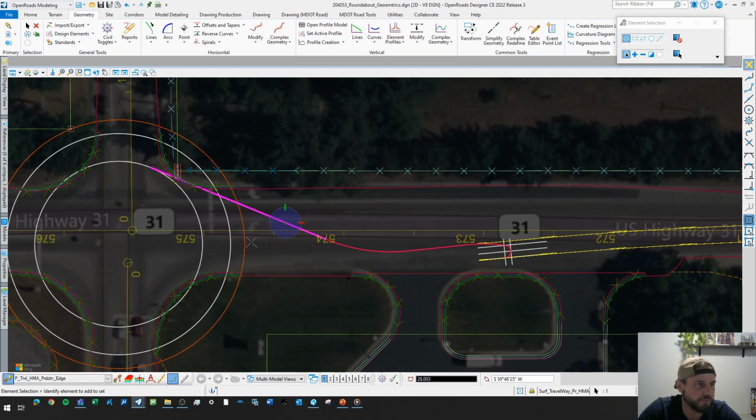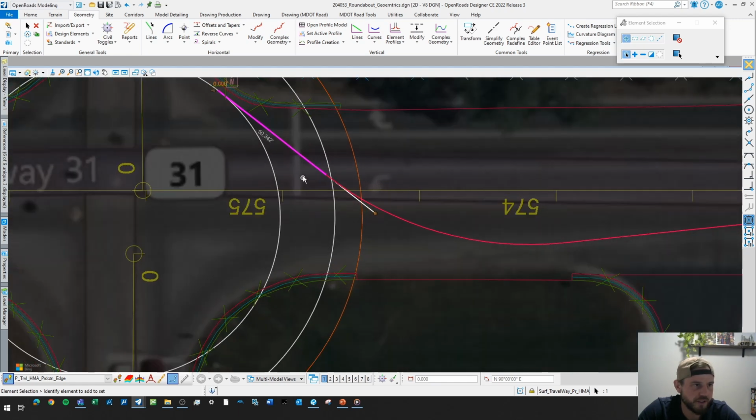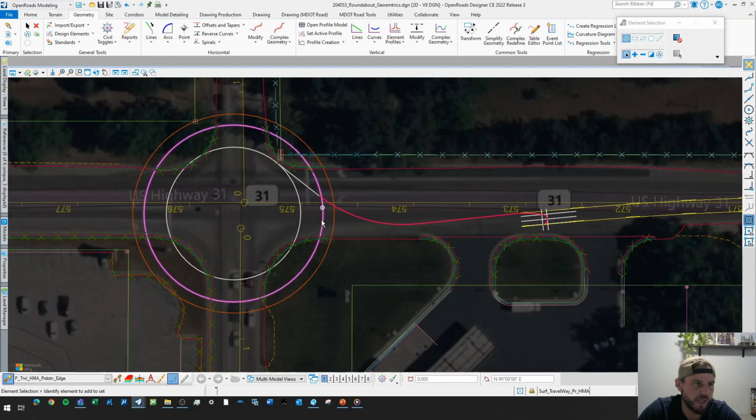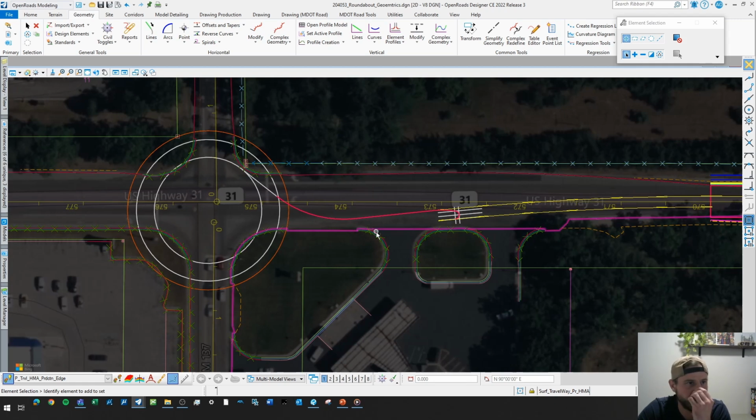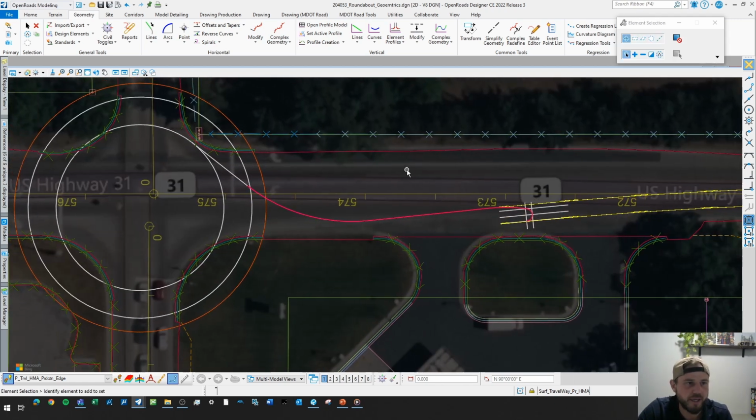For this one, since what I was talking about is this is going to be a single. This is actually the circulating roadway width here, not the total ICD. These ones will come into this outside ICD, but the east and west leg are going to come into, to make that a single lane. So you can adjust that line then, and now this curve is shooting that traffic right into the roundabout. So I don't mind that as a starter. I think that looks pretty good.